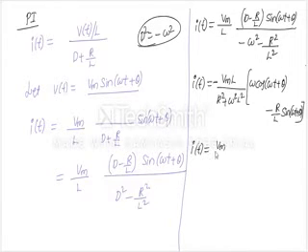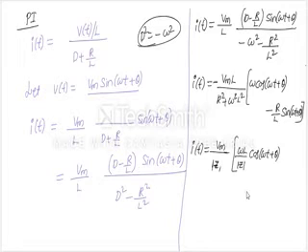This is Vm by, I can write this as Z, mod Z square into, I can say this as omega L by mod Z, sorry, one Z I can remove here, mod Z into cos of omega t plus theta minus R by mod Z into sine of omega t plus theta. Check it.